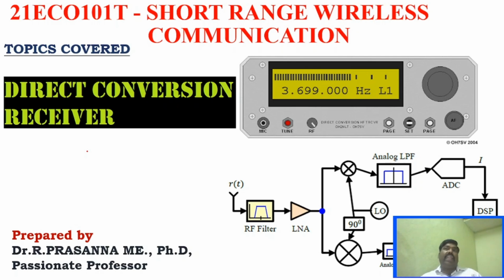And the greatest advantage of direct conversion receiver is it does not suffer from the image frequency problem, which is a significant problem in super heterodyne receiver. We have to do a lot of steps, a lot of filtering methods to overcome those image frequencies in super heterodyne receiver, whereas we don't have the image frequency problem in direct conversion receiver.